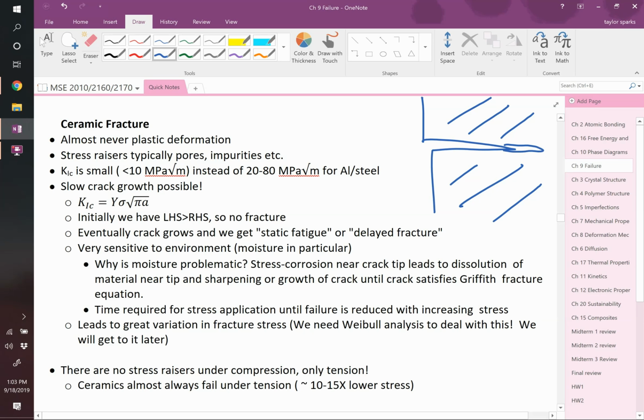Sometimes you can actually see this happen really quickly. If you have a quartz tube and you want to break it because you need to cut it, you can actually put it in a tile saw, a diamond saw, and you can cut through it if you want. Or you can actually just scribe it. What's a scribe? It's just a diamond, right? A sharp tip of diamond, and you scrape it along the edge, and then you can cause that thing to break. You can try and break it with your hands, but it actually gets much easier to just lick your finger and you wipe it along the edge of that crack, the score that you just made, because the liquid right there goes into that crack tip and very rapidly starts to dissolve right at the crack tip, and it will actually break at half the level basically. So it's much easier to crack these things.